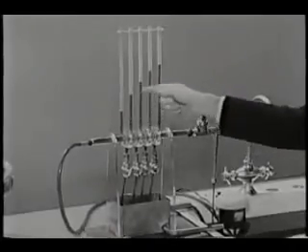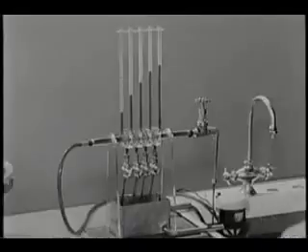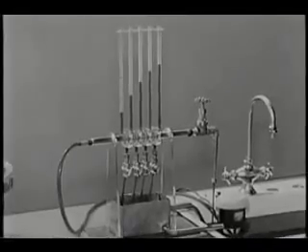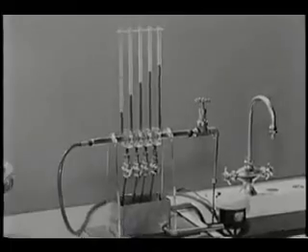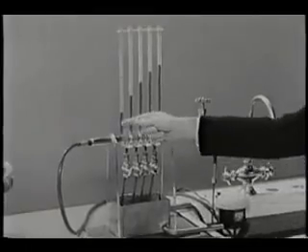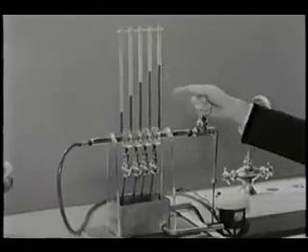The pressure now rises. Since the area is constant, the velocity is proportional to the volume flow. Therefore, the velocity decreases. It is this streamwise deceleration which produces the streamwise rise in pressure.